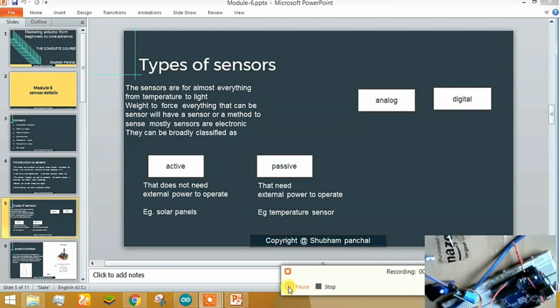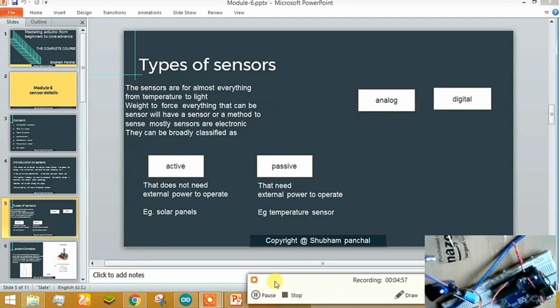Passive infrared sensors are used for detecting the presence of a human in the range, but they do not detect the value of the presence, so they cannot give an output as a measurement. They give the value in the form of ones or zeros, or you can say a low signal if no human is present and a high signal if a human is present there. Okay.